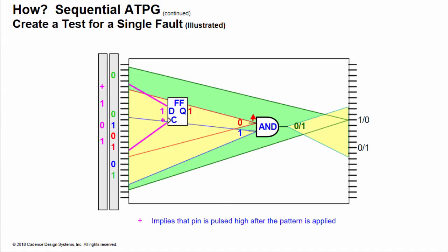In a realistic case, we would have an indeterminate number. Application of a single fault test might require moving a finite state machine or a counter from an unknown state to a known, desired state. This can take many patterns and clocks. So how are we going to resolve this?